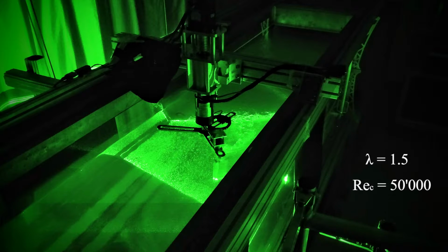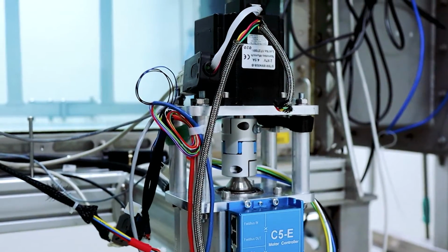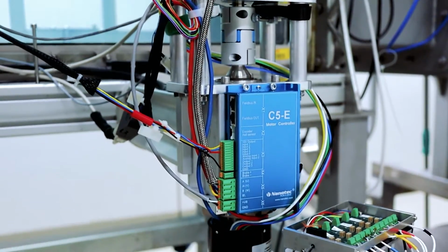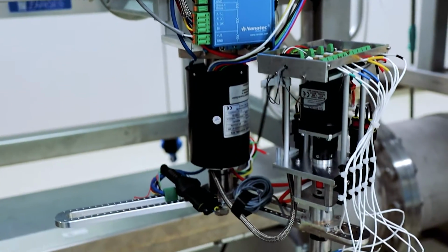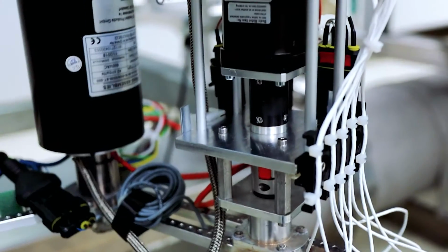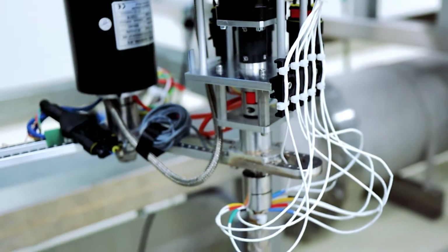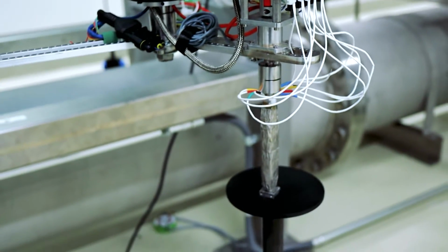We keep the blade in the field of view at all times thanks to a rotating mirror system, which we'll look at in more detail in a moment. But first, let's have a look at our wind turbine model. Our scaled-down Darrieus wind turbine model is motor-driven. It has 2 interesting features. Firstly, this stepper motor here allows us to continuously adjust the blade's angle of attack independently of the main rotation.